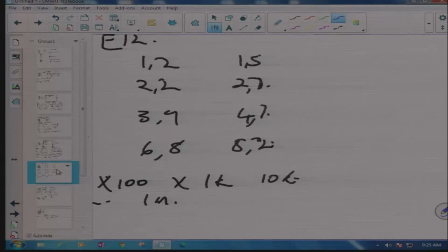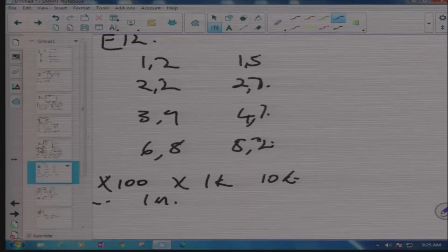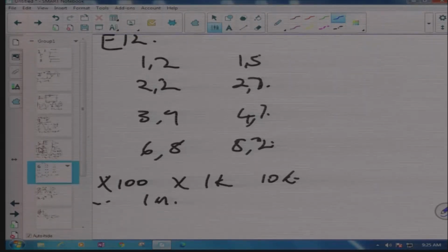My dear students, the next other thing that we looked at was the E12 range. What is an E12 range? It's a set of 12 standard resistors which are available off the shelf. All of them, their tolerance is silver, meaning it is 10%. What are the values? 1, 1.2, 1.5, 1.8, 2.2, 2.7, 3.3, 3.9, 4.7, 5.6, 6.8, 8.2. These are available in multiples of 10, 100, 1K, 10K, 100K, 1 meg off the shelf.